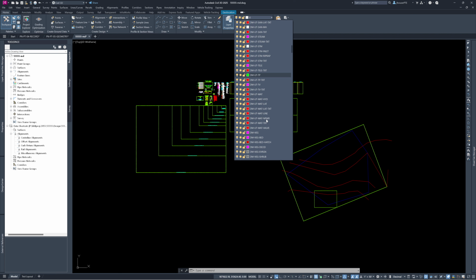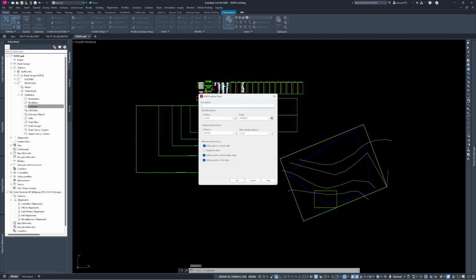All right. I already have a proposed surface through the template, so we can add those contours as definitions. Also, lately I've been dropping our mid ordinate down to 0.01, which is very tiny. I hate to do that because it will slow things down. If it's a smaller project, I would recommend changing to 0.01. A larger project like this is going to be 200 scale. We probably want to keep it at 0.1. That cuts down on the amount of calculations, although it also makes the contours not quite as smooth. But we'll get there.